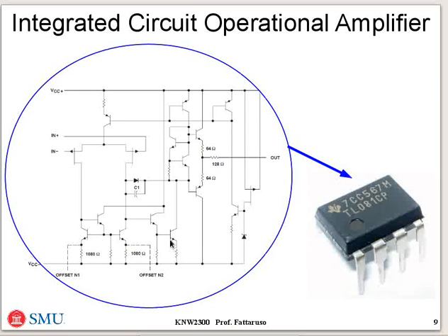Of course, integrated circuit technology gives us the capability of manufacturing a circuit where all of the active and passive devices, resistors and capacitors, and here's a diode, are all integrated together on one tiny silicon die, which is contained inside this plastic package here. And this particular op amp can be bought for under $1, and it reduces the component price of the active devices to just pennies a piece. And this is a very, very high gain amplifier that we'll be making use of.